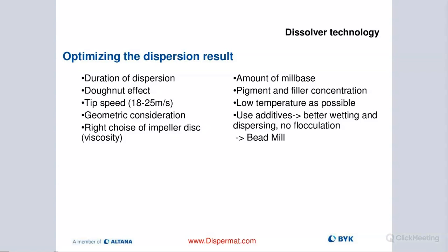So therefore, it's important that you have the right type of vessels. And if you are pre-dispersing material that is very viscous, I highly recommend that you also use some sort of cooling, because you're going to put in a lot of energy. And again, when you're milling, you're going to need it anyways, so you may as well just get it up front. These are jacketed vessels that allow you to hook up a chiller or tap water, which will circulate through the vessel and keep the temperature as low as possible.